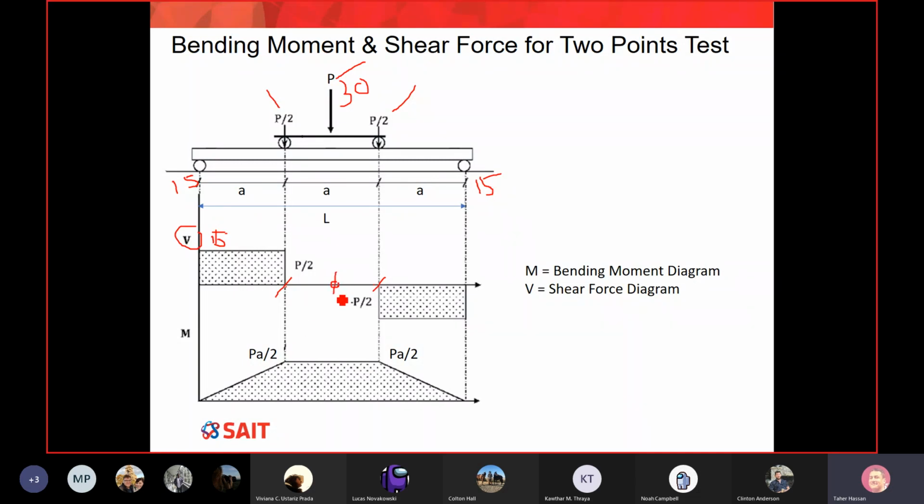And that's exactly the secret. Why do we do 2-point load? Because you can see where my gauges are, from 1 to 7, they are all here. Those are my strain gauges. So I'm asking you, do those strain gauges measure or have any business with the shear forces? Remember, they are installed in the middle, and in the middle, there is no shear force. It means when I measure strain here, those have no business with shear strains. Okay? You guys following? The reason why we have 2-point load is that when we have 2-point load, this section of the beam in the middle will be under only bending moment, no shear force at all.